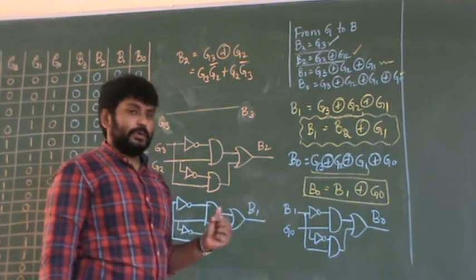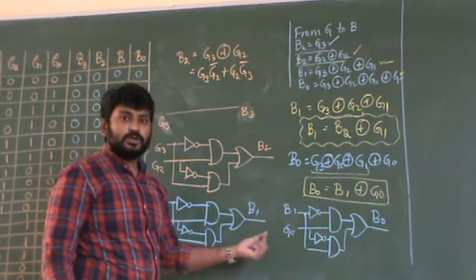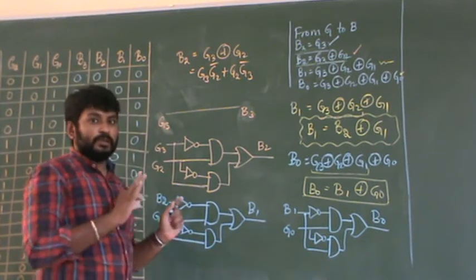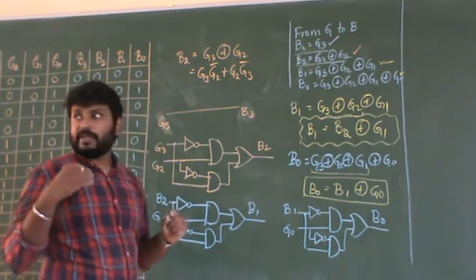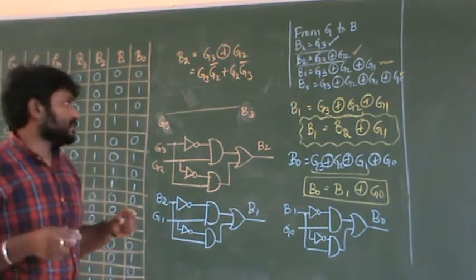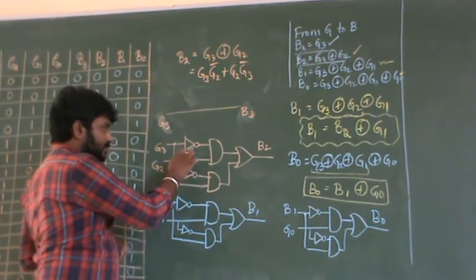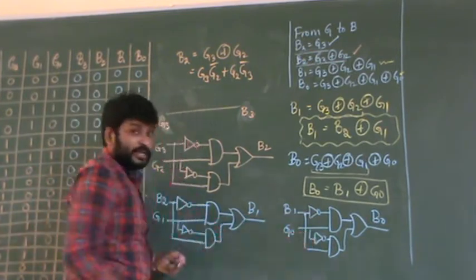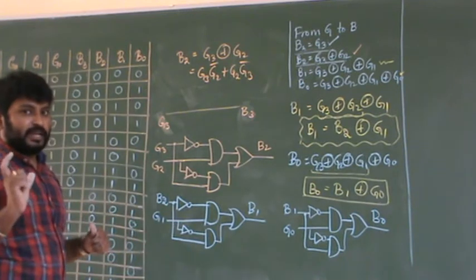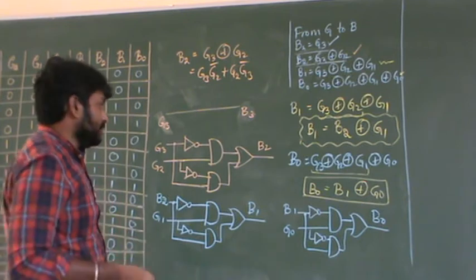So these are the only four circuit diagrams you have to implement. If you want to implement this circuit diagram, you cannot implement each and every circuit separately. All the circuits you have to implement at a time. Whenever I explain the practicals, then you will understand. So let me write down the pin numbers. How many NOT gates are there? 1, 2, 3, 4, 5, 6 NOT gates. We will use only one IC because in one NOT gate IC there are 6 NOT gates.